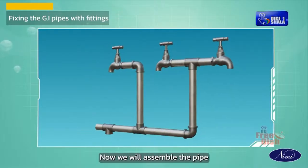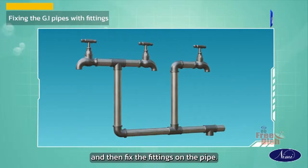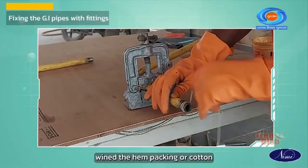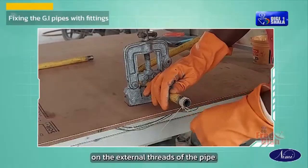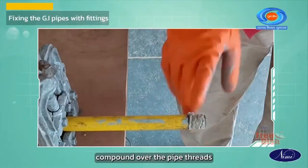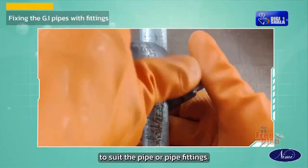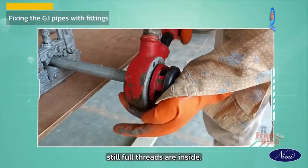Now, we will assemble the pipe and the pipe fittings and then fix the fittings on the pipe. Hold pipe 1 in a pipe vise. Wind the hemp packing or cotton thread material on the external threads of the pipe. Apply sealing compound over the pipe threads and adjust the pipe wrench to suit the pipe or pipe fittings. Continue the screwing process till full threads are inside.